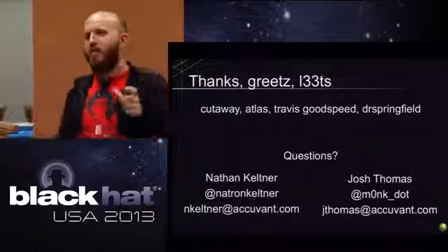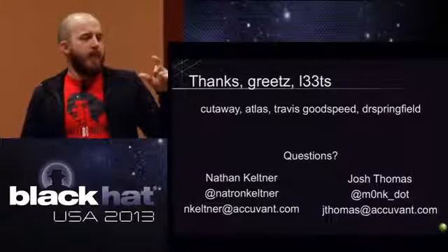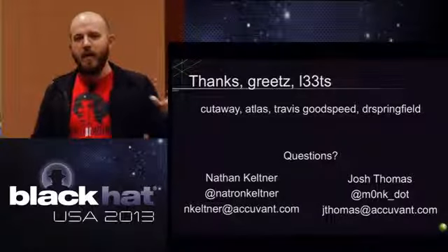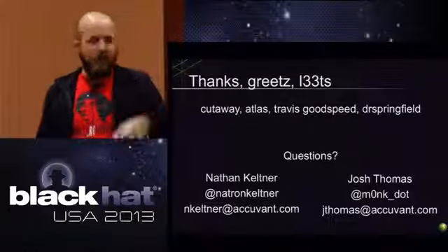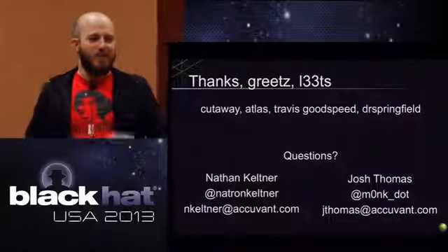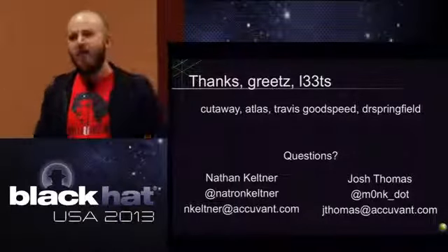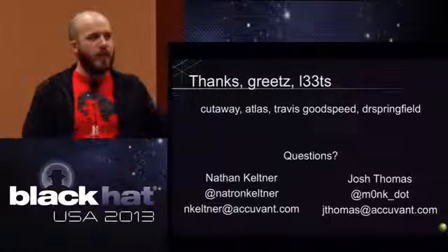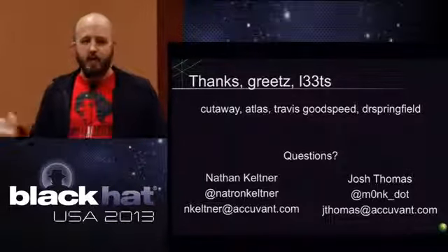And finally, in one place, you find a remark from the author that says, because of normal electromagnetic interference, like in storms and whatever else, the execution pointer gets corrupted all the time. So just in normal usage of the thing, the instruction pointer will jump someplace else and it just goes all crazy. And it's okay because there's a hardware watchdog that is paying attention, and it'll just reset it if it gets too out of whack. And that's not a big deal for that.